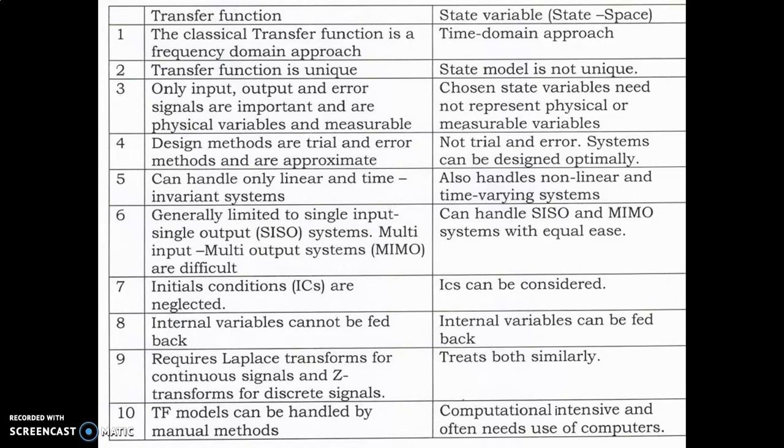In the transfer function approach, initial conditions are neglected, but in state space analysis, initial conditions are also considered. In the transfer function approach, internal variables cannot be fed back, but in the state space analysis, internal variables can be fed back.